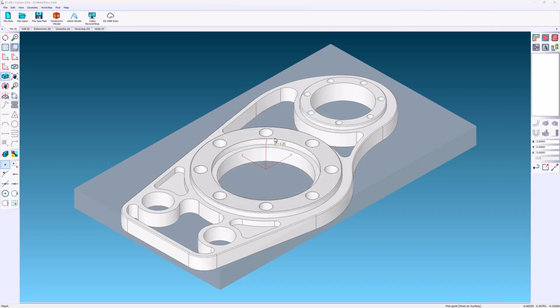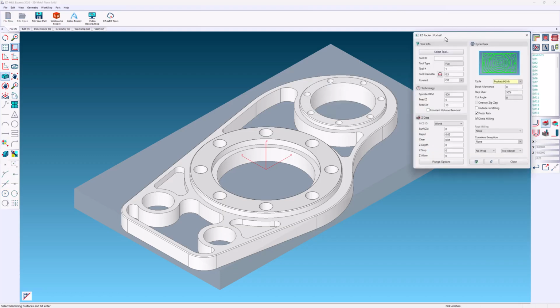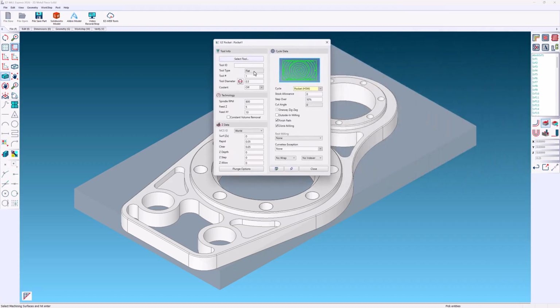You can access the tools you added to the tool library within any operation. The tool type is displayed and can be changed in the background. The tool number and diameter can be modified on the fly without the need for preset tooling. The length of the tool is generated automatically, assuming you are confident that the tool holders won't collide with the workpiece or clamps.